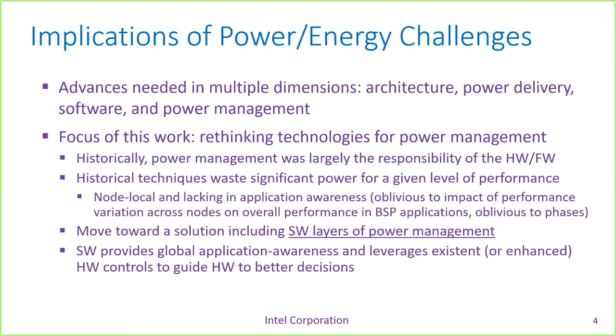For example, if you're in a memory limited or a communication limited phase, it makes no sense to run the processor cores at full bore. They'll end up just generating memory references or communication operations faster than those other subsystems can satisfy the requests. So it's awareness of those sorts of things that's lacking in traditional hardware and firmware-based techniques.